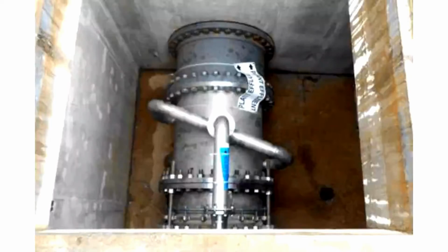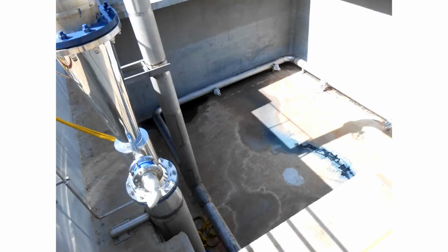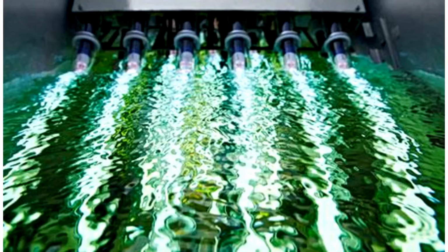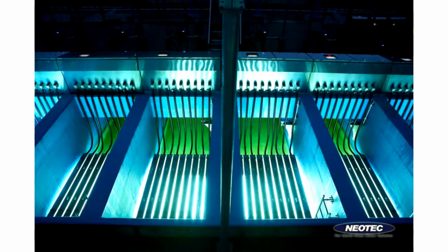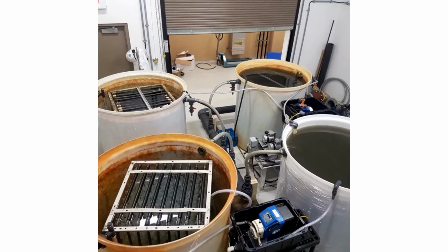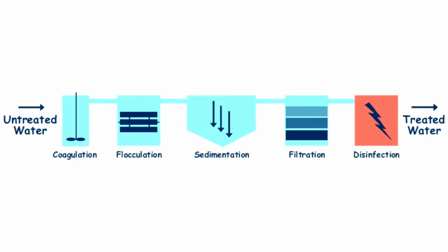Step 8. Oxygen take-up. The treated water, now in a very stabilized high quality state, is aerated, if necessary, to bring the dissolved oxygen to permit level. After this step, the treated water passes through the effluent outfall where it joins the Oconomowoc River. The water discharged to the river must meet stringent requirements set by DNR. Pollutant removal is maintained at 98% or greater. Depending on location and utilization of treated water, the disinfection process may change from chlorine, UV radiation and ozone.